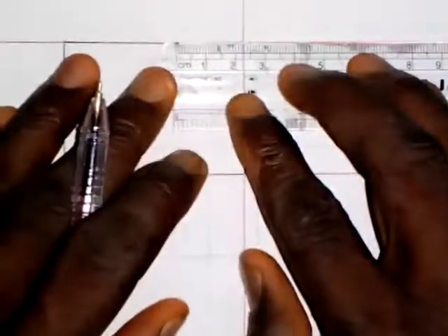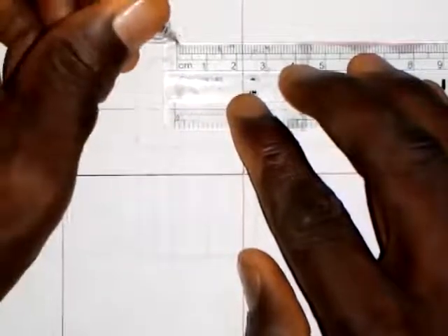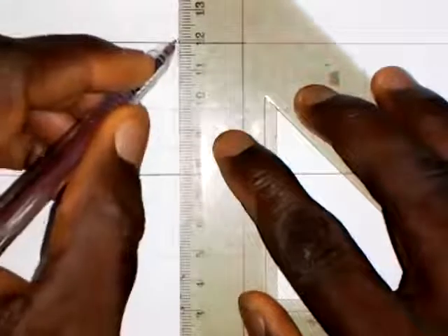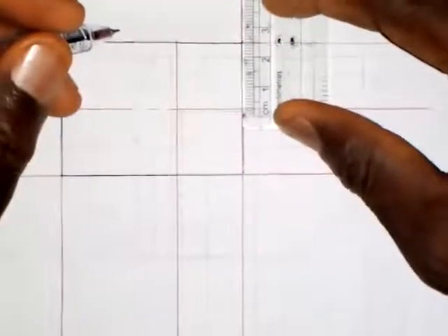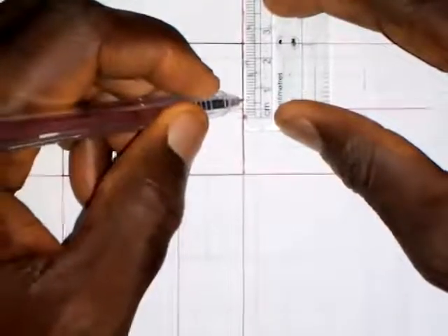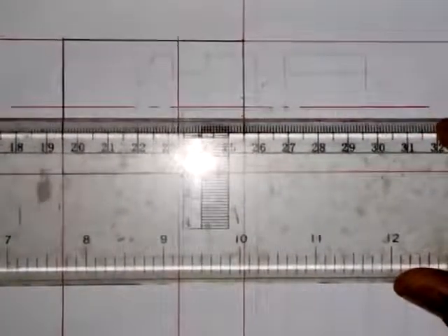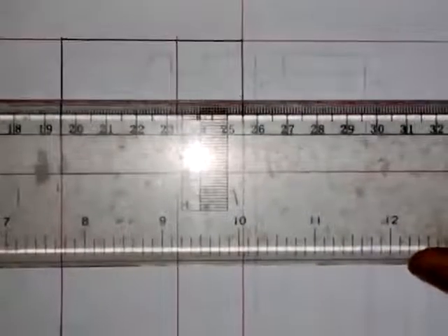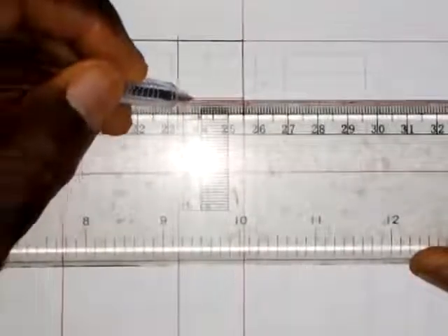So what we are going to do now is take a measurement of 22 millimeters from here, because the length of the web, which is going to give us a rectangle in the plan, is 22 millimeters from the edge here. So draw a vertical line from here down. Then from this center line, the thickness of the web is 6 millimeters, so we take 3 millimeters down and 3 millimeters up like this. I will now draw the horizontal line. This horizontal line goes to this side, and I will also draw it here and it goes to this side.